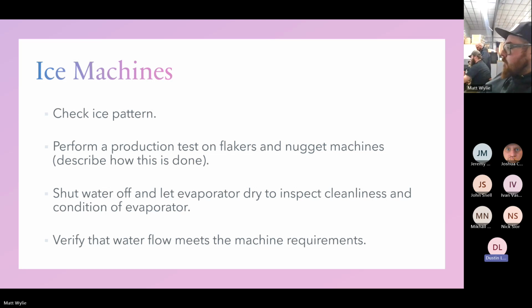But from what I'm finding, most of the valves ending in a C are listed as higher temp or medium temp applications, and everything ending in a Z is pulling up as low temp. Does anyone know what the KT or the 53 is? If you type in 53 SC, it's a 404 medium temp valve. If you type in 53 SZ, it's a low temp 404 valve.